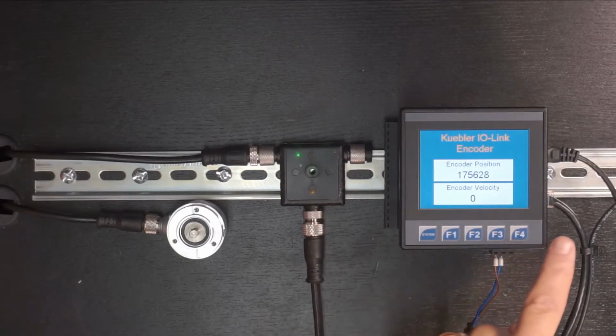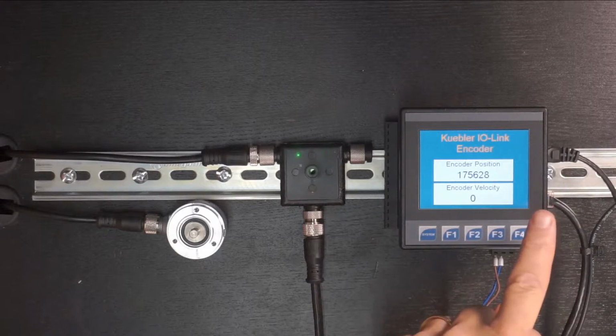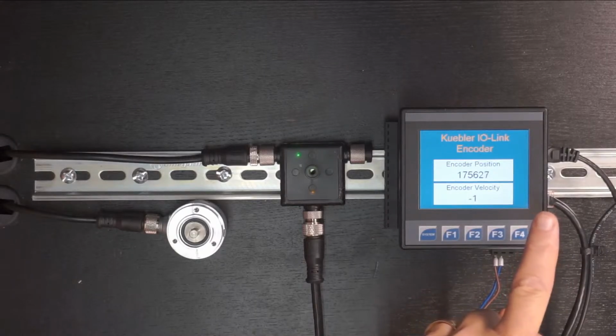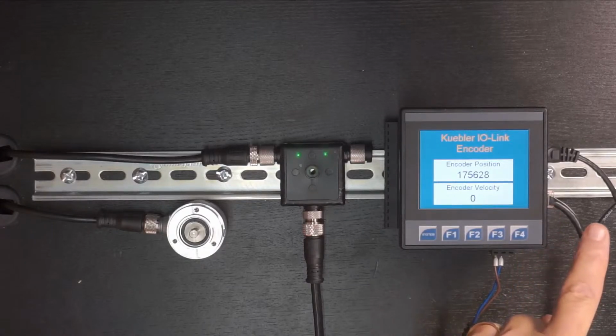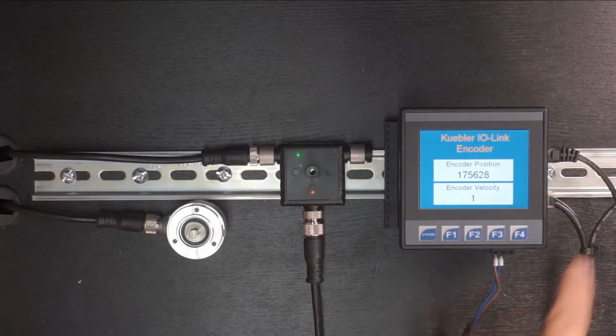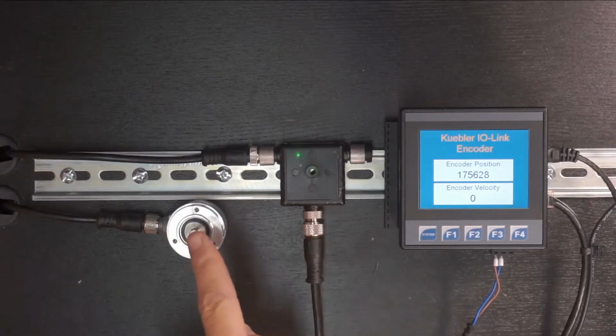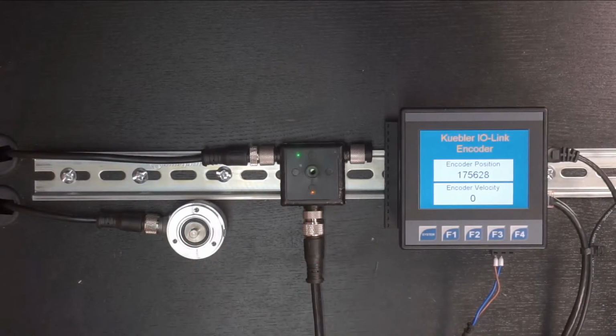And then one upper arm of the Y is connected to MJ2 via RS485 here. Okay, and then the other leg of the Y, other arm of the Y, I guess you could say, that's actually running off to 24 volts DC to power the master, and through the master, also the encoder. Okay, so that's what it looks like at runtime.